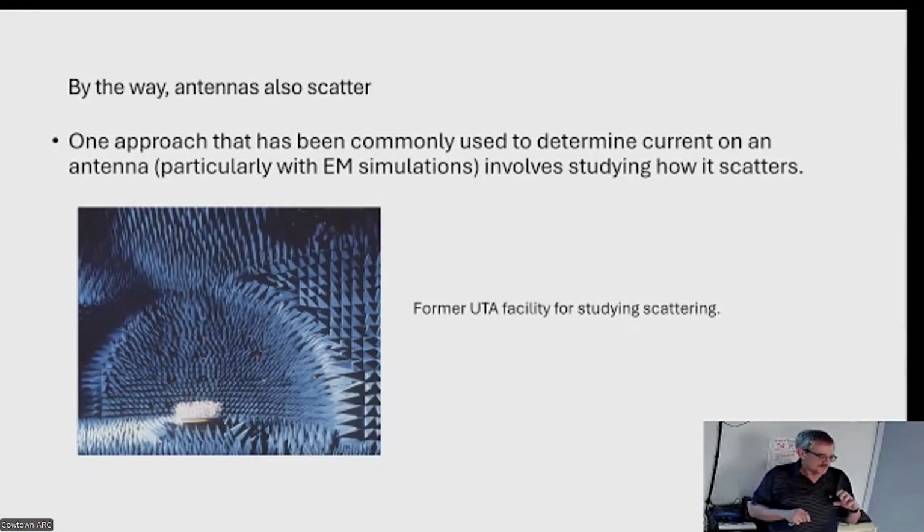In the case of an antenna, you still include that impedance, but that impedance is just energy that's lost because it's re-radiated. So you're capturing the wave, part of it's re-radiated, and part of it's delivered to the receiver. Part of the trick is to keep that energy from being lost to re-radiation. Well, you really can't. Okay. You're stuck with it.